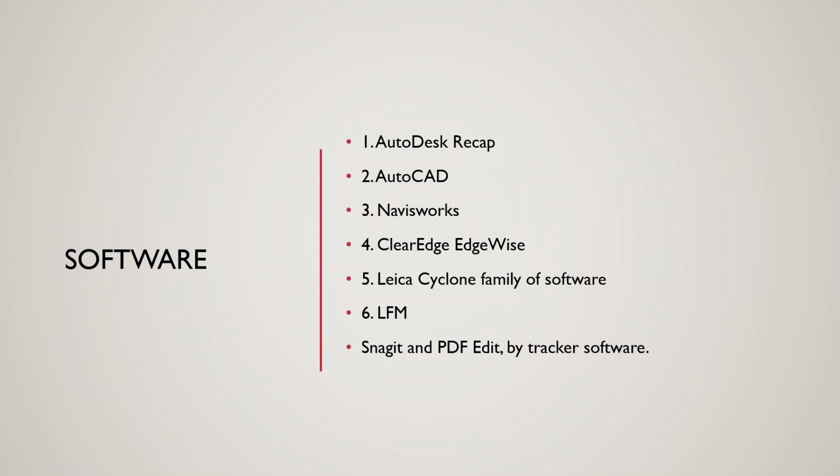One is that these files are large. A small laser scan is about 8 gigabytes. A large laser scan that I've worked with is in the neighborhood of 500 to 800 gigabytes. So my recommendation, if you're starting out, is to get a RAID drive, a redundant array of independent disks, and use it like a local drive. Get 4 or 5 or 6 terabytes put into it, and use that locally.